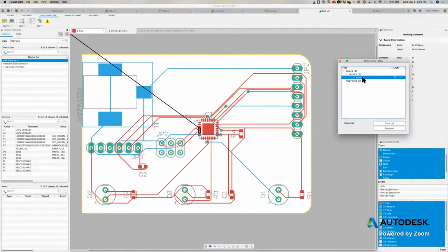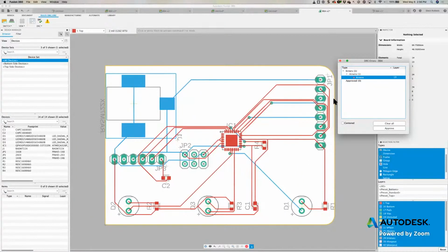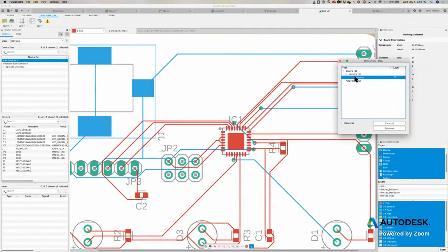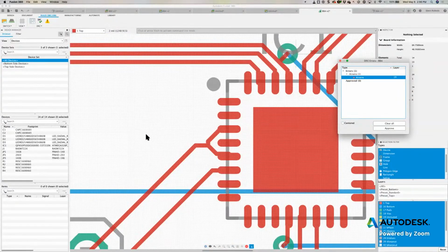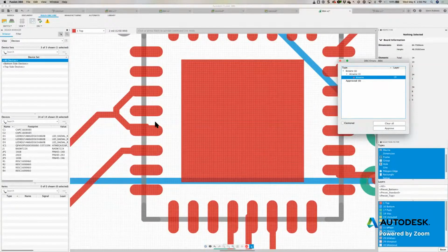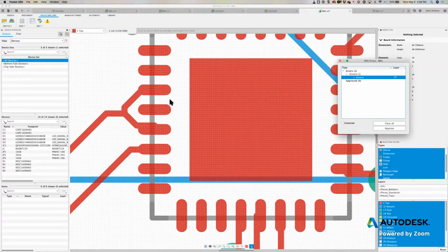Now let's go ahead and take a look. I could double click it and it zooms in on it a little bit. It seems to be a really, really thin line that you could barely even see. It's right there. There's a line. So there's a routed line, and apparently the way this is routed, it's kind of blocking it. So we would actually rip this up.